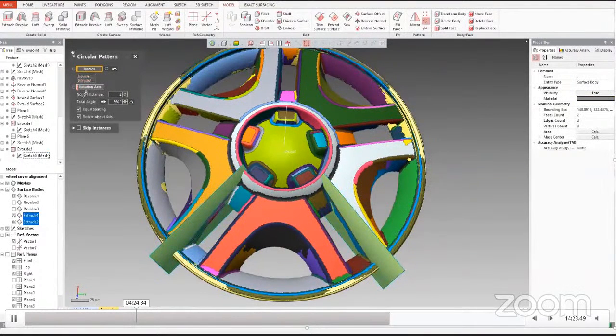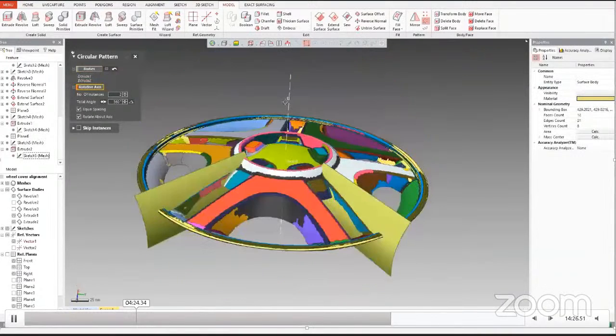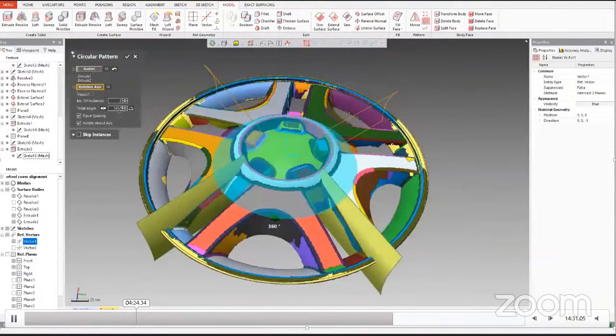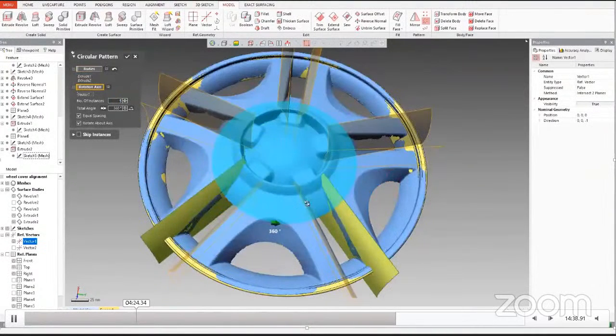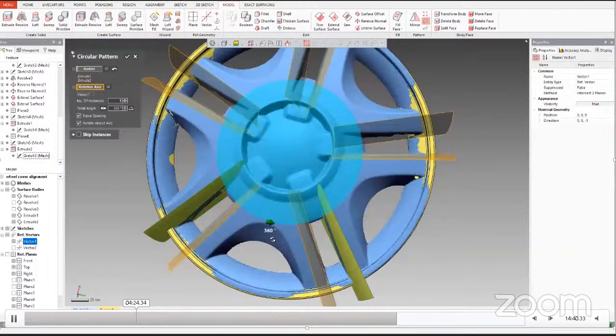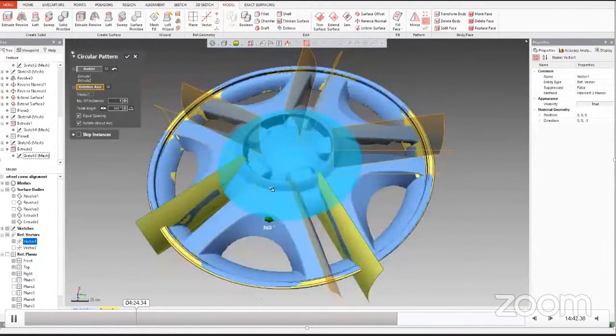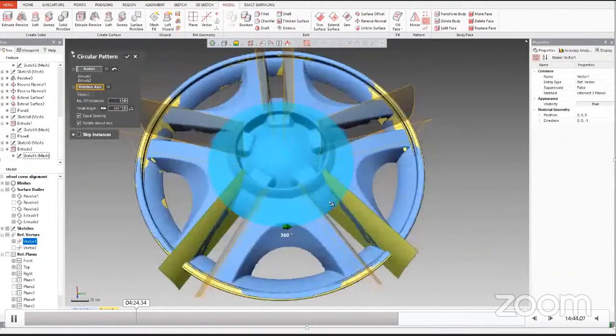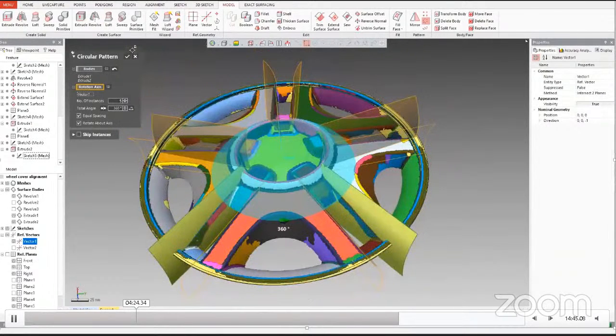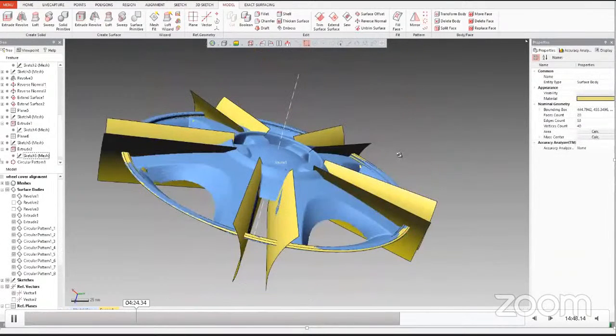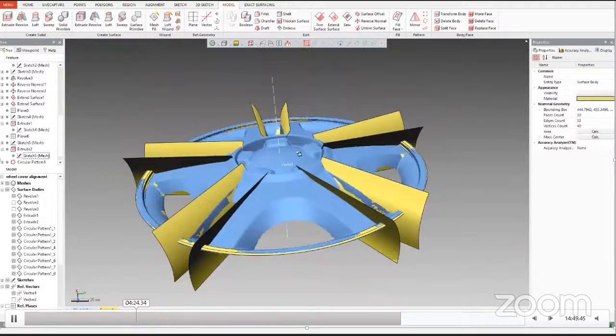So I select the central axis, which is the vector 1. So I will select how many patterns there are and to what degree. So there are 5 patterns required for this one, and it should be a complete rotation of 360 degrees. And now I will click. It seems good, so I will click OK. And now we have all the walls at the side of the ribs.